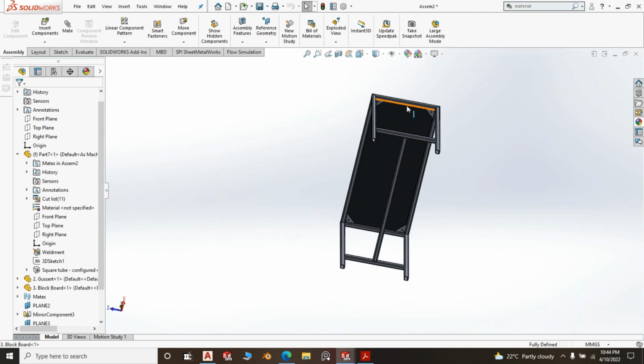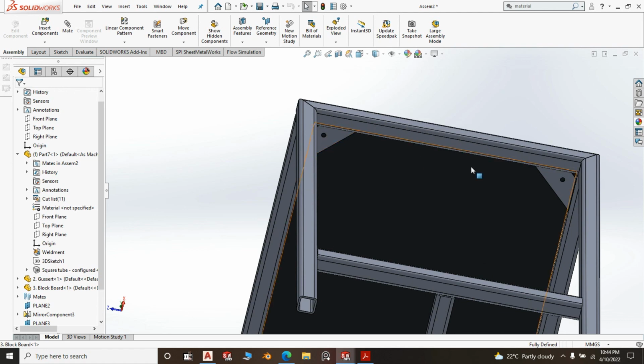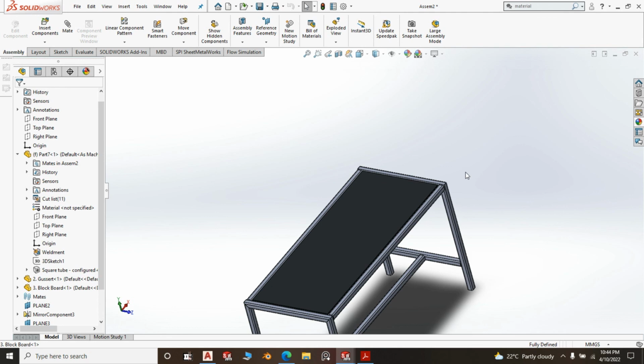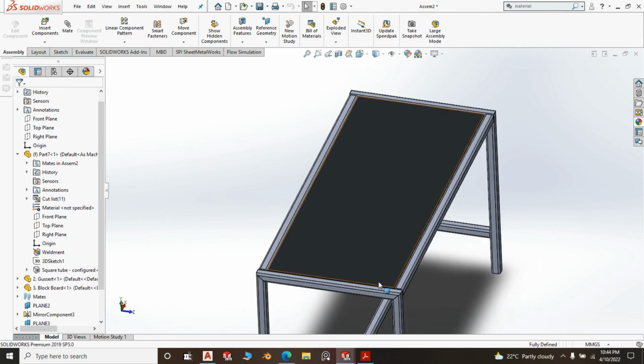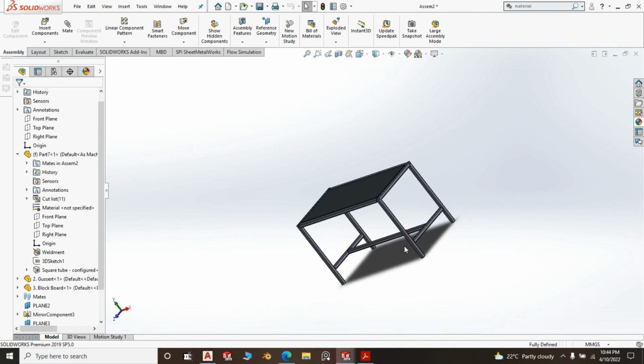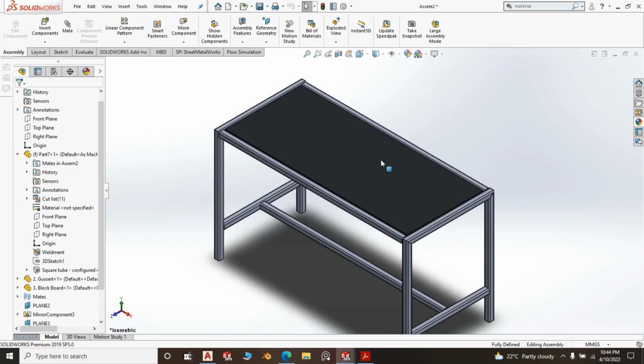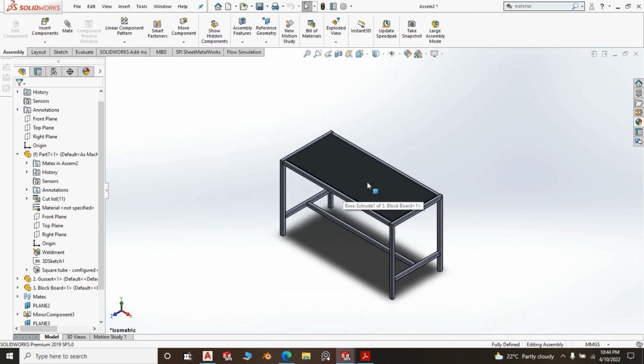Now, your board, those holes come in handy. Fasten your board there, but again, you don't want your bolt or whatever means you're using to fasten to protrude and interfere with the granite. And the granite, you stick it with adhesive to this board, right? To the board, use adhesive. And again, this also acts as a backing.